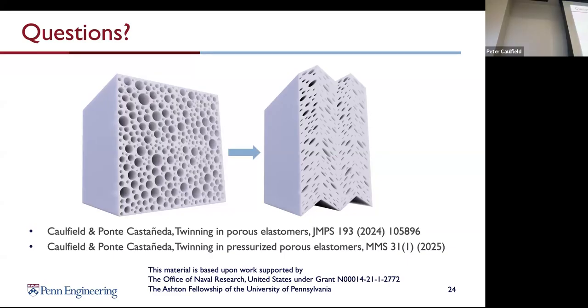If you're doing periodic homogenization, the simplest thing you can do is just choose one unit cell where your material is periodic and see what happens to that unit cell, and then just assume that the material behaves like that unit cell, just multiplied in all directions. So you have periodic boundary conditions applied to the unit cells.